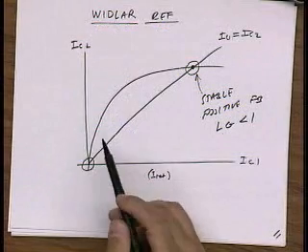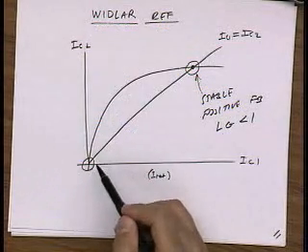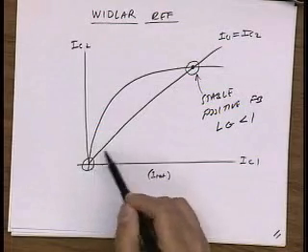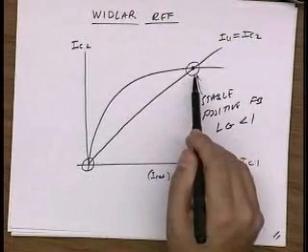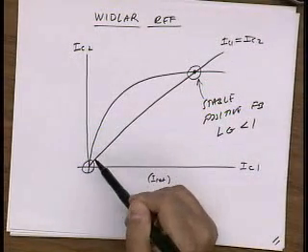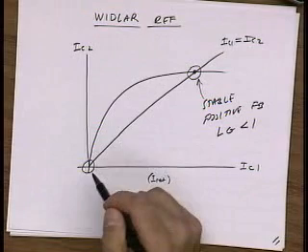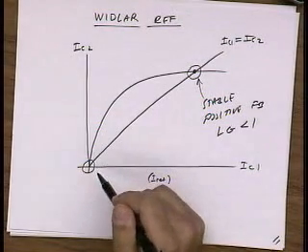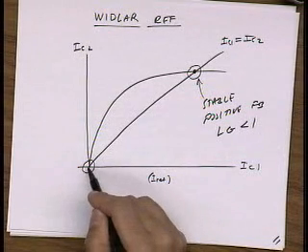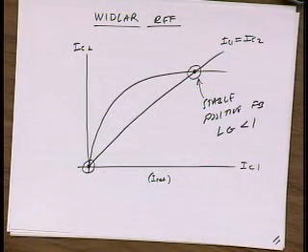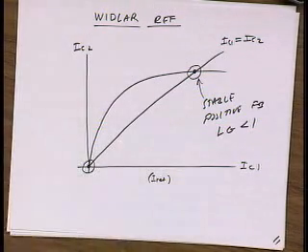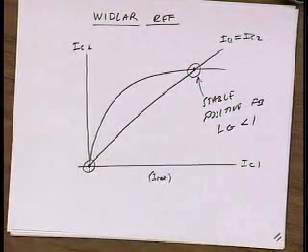Now, theoretically, if any noise voltage just kicks it enough, just noise in the circuit, it should get out of this. It should actually end up going here. So it seems unlikely that the circuit will remain in this dead state. But the problem is that when the circuit is dead, there's no currents flowing, so there is no gain. So if you do end up in this zero current state, even a noise voltage that kicks it will not have enough loop gain to get it out of this dead state because the current levels are so low.